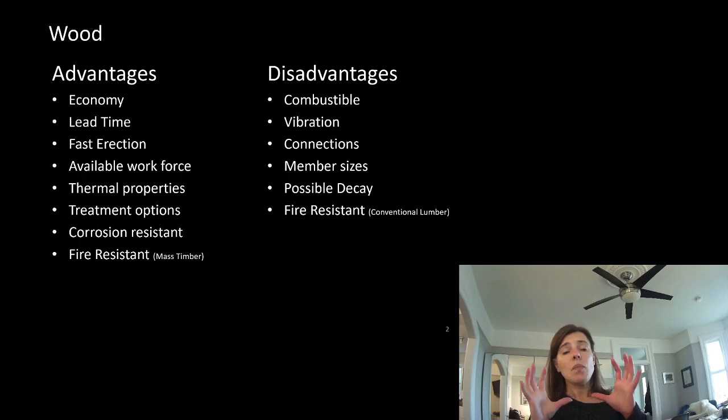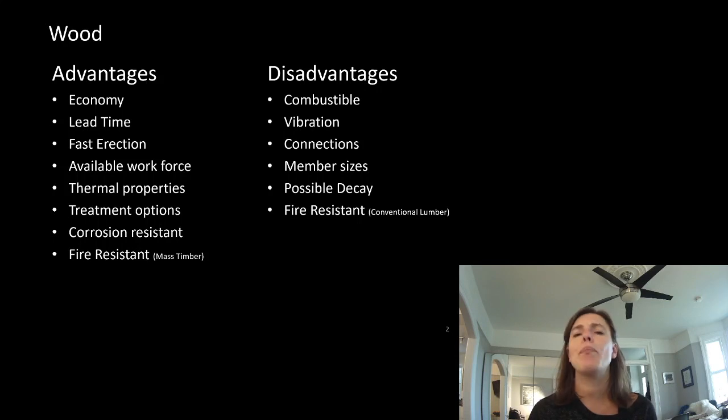It is big enough that when it burns, it will build up a layer of char that will actually act as an insulator from the fire, and it will help protect it. So you can't access the other wood that needs to burn. The second part is that it's so massive that as it burns, you're still left with structural capacity inside. I think the fire rating is wood burns at 1 inch an hour for framing.